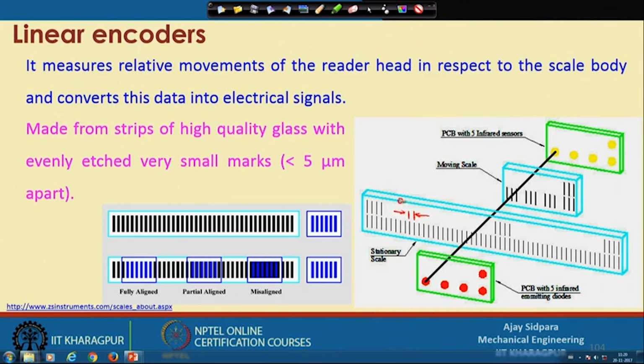So, if you think about 0.1 micron to 1 micron, the first thing is how to make this particular thing. There are lithographic processes available, and etching available. What you have to do is create one particular mask out of different processes. Electron beam lithography is available, and a mask generator.